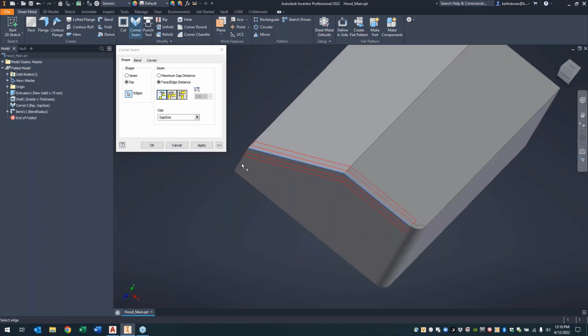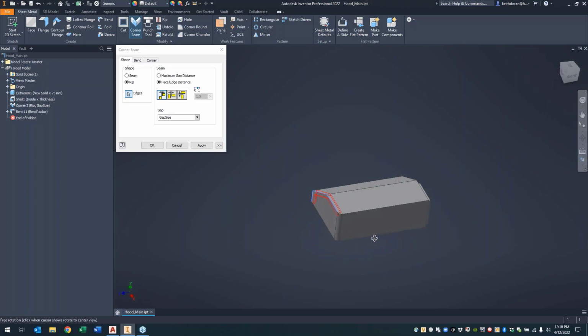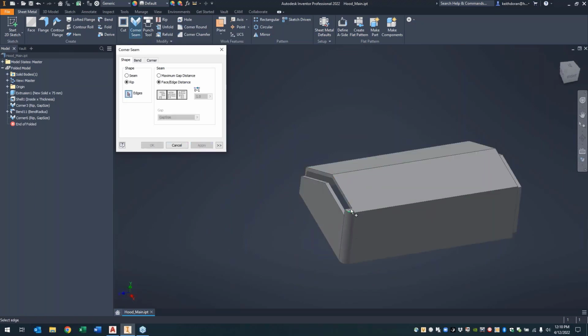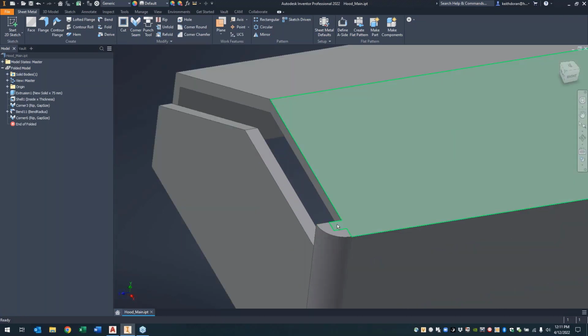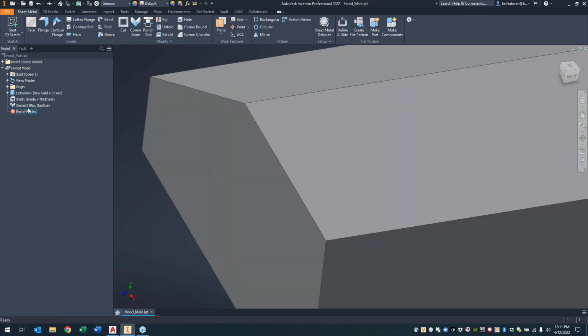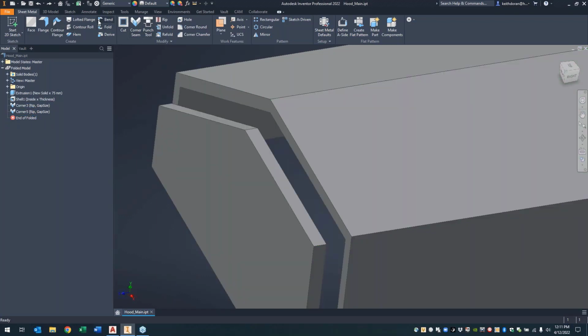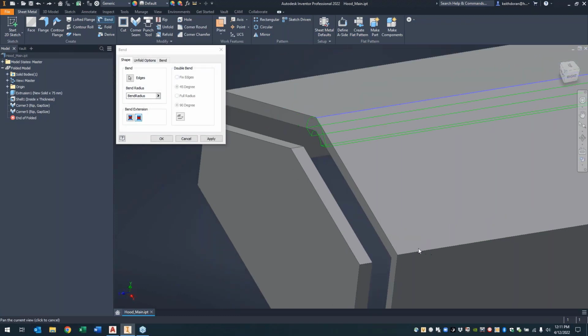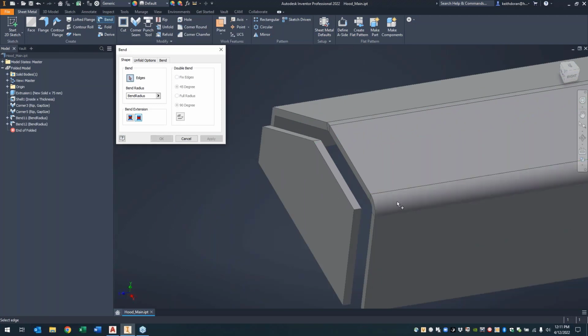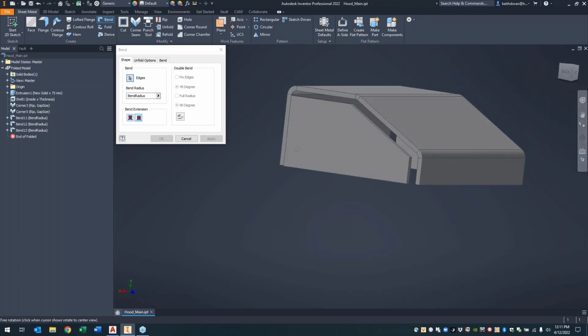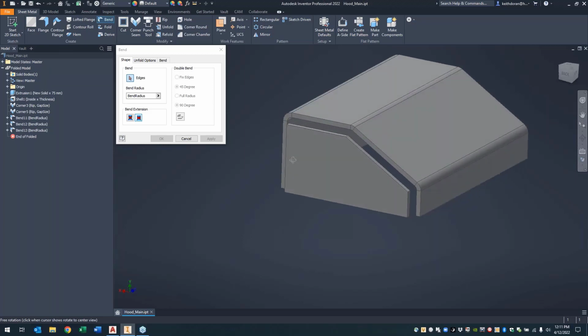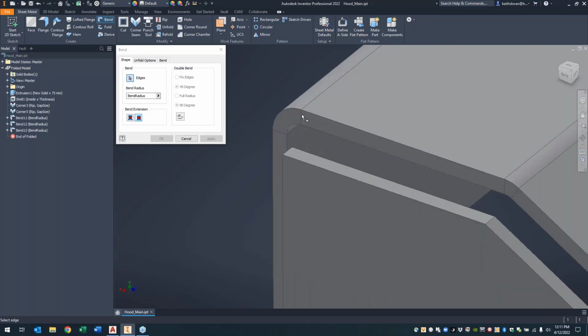What I was trying to show is that you can separate the entire body apart if you need to. And it might be because I didn't do the tapers first. It's not going to flatten that way because it's got that internal gap. Let's do the bends where the bends are. So we know these bends exist, so we can apply those. That might be the reason why it's failing. I'm doing the order of operations a little bit abstract here to try to force it to make different shapes. But now that I have those bends in with the actual radii, yeah, that's why.